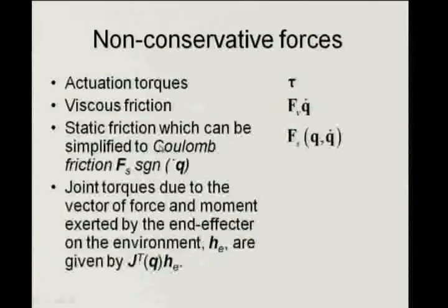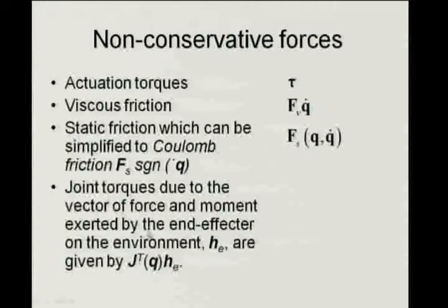Okay. In Coulomb friction, it is dependent only on the sign of q dot. So that is what I am writing here, and this Fs will be a vector of loads, which can be calculated based on other parameters. So this is a form of that, and then in the last part we already looked at is that if your end effector is pushing or pulling at something,